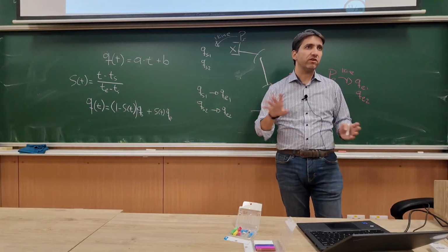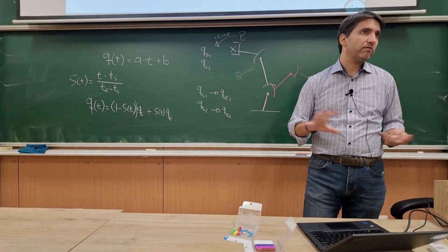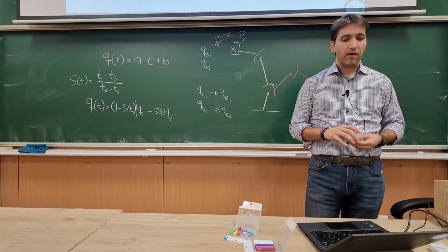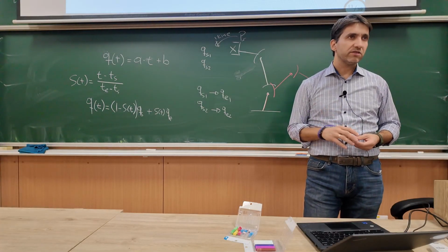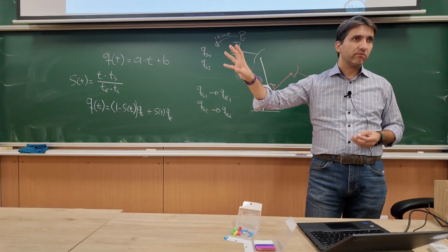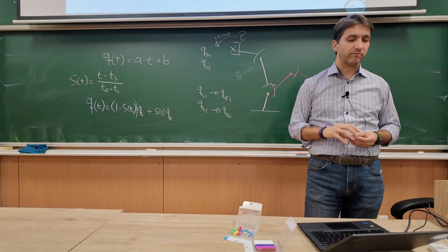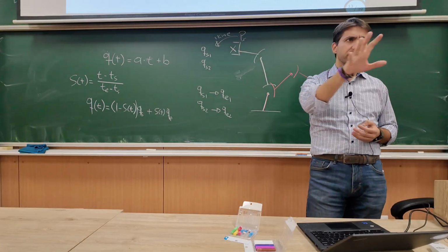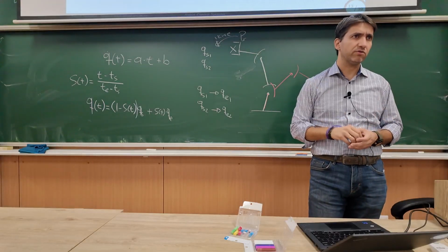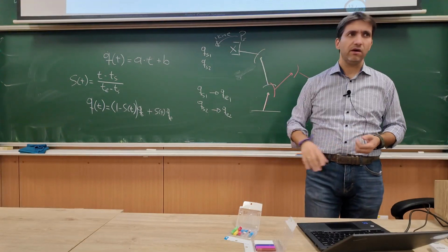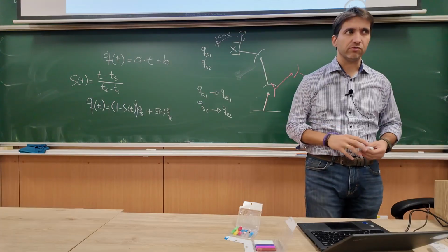We can always move the joints because they are just moving independently. The issue with singularities happens when we are controlling the end effector. But yeah, we could stop in a singularity position, and then if we switch to another mode of control, maybe we'll have issues.